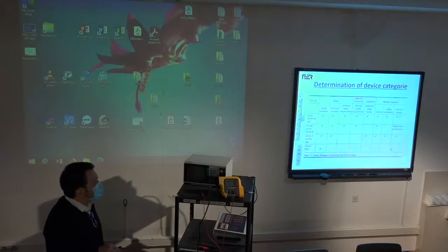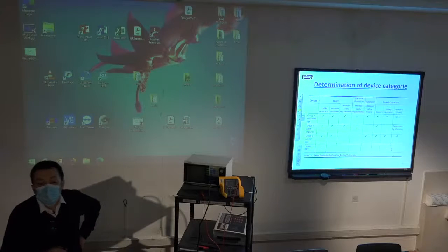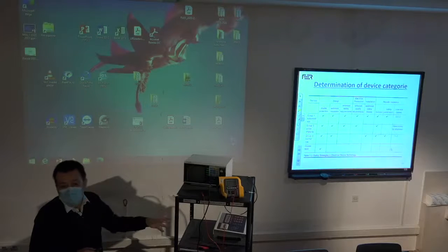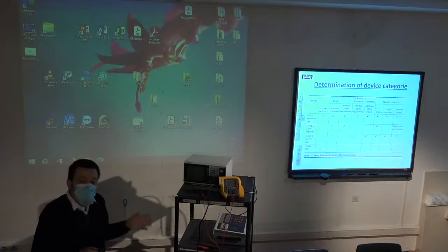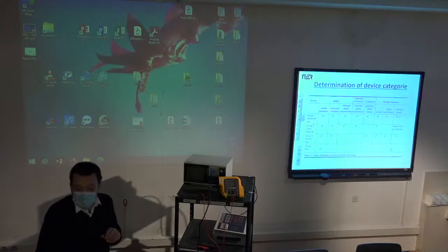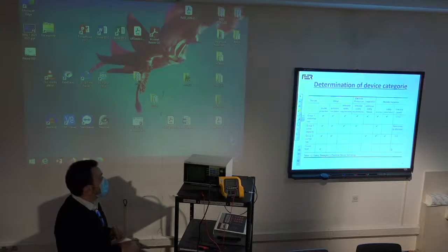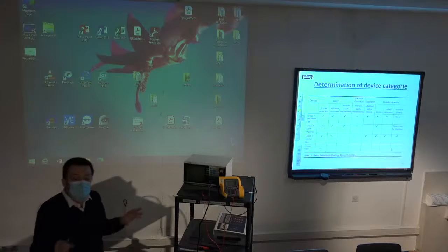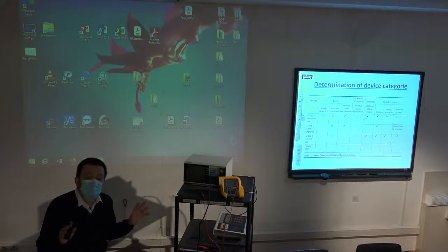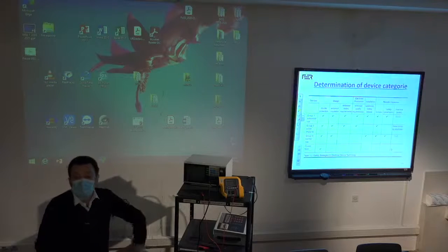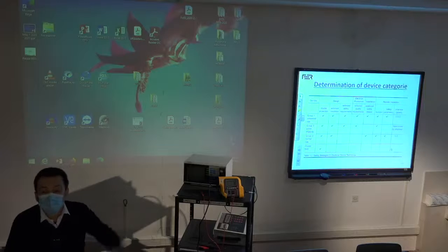So you can see group 1 with enhanced risk is all those devices that are invasive, either with radiation or with the power of ultrasound or by the electrical current that is used for cutting tissue or something like that. The group 2 is active implants, so you already know what are active implants. The group 3 is normal risk. Normal risk, it is ECGs, EEGs, all these devices that are mainly diagnostic, where you do not push any power through the patient. And then finally household, that means blood pressure meter that you or your grandmother has at home and so on.